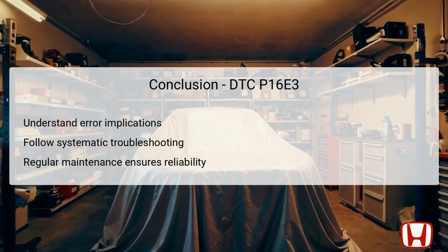In conclusion, understanding DTC P16E3 and its implications is crucial for maintaining the long-term reliability of the Honda CR-V. Following a systematic troubleshooting approach is vital in diagnosing the root cause effectively. Each component involved, the PCM, 12-volt battery sensor, and LIN communication, plays a significant role, and diligence in inspection can prevent further complications.